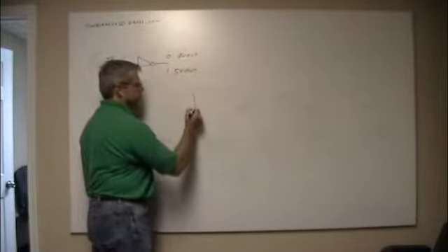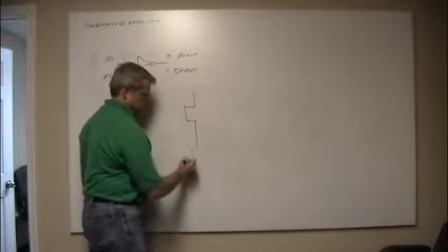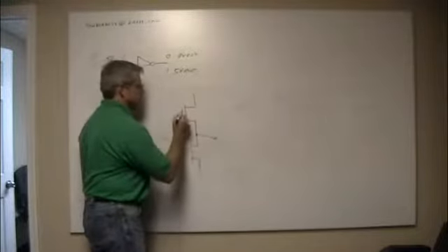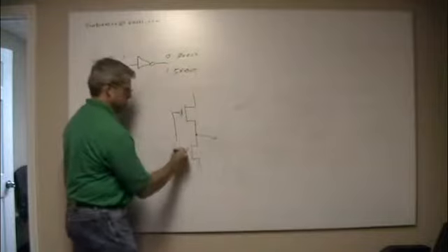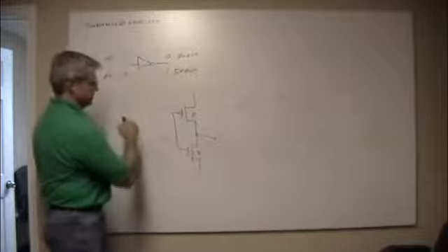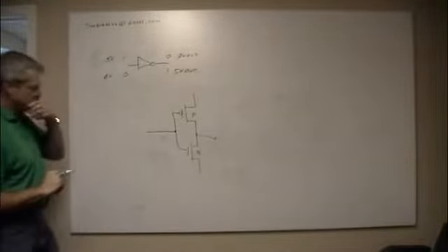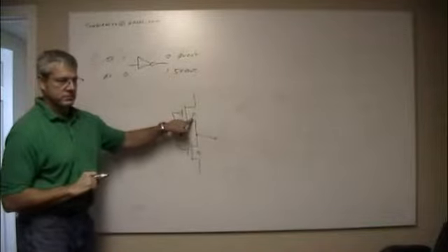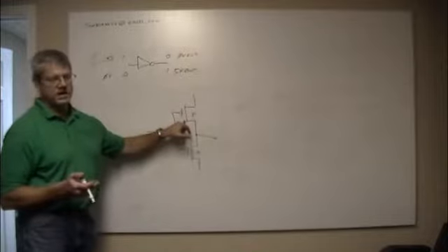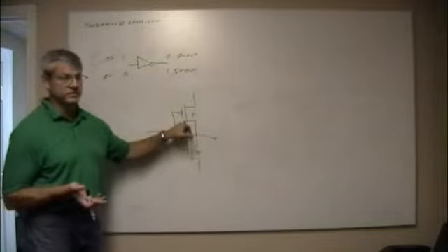Inside the circuit, what you see is 2 FETs. The output is taken here. I'm using this notation. So this is the P FET, and this is an N FET. The one that I drew earlier was an N FET. And what this is showing is that there's no connection through. This is not infinite resistance, but for all practical purposes, it's infinite resistance.